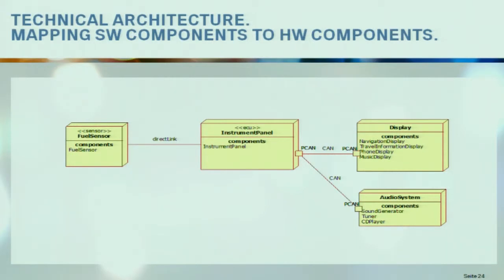Okay, so next step, it's getting deeper and deeper. At the end, you have software components, so you know how the software interacts with each other. Now you have to map and bring this software to hardware, and that's exactly done here. You think about connections which are directly linked, which go through buses, and you more or less partition on different things like ECU load, on timing issues between the software components about the partitioning.